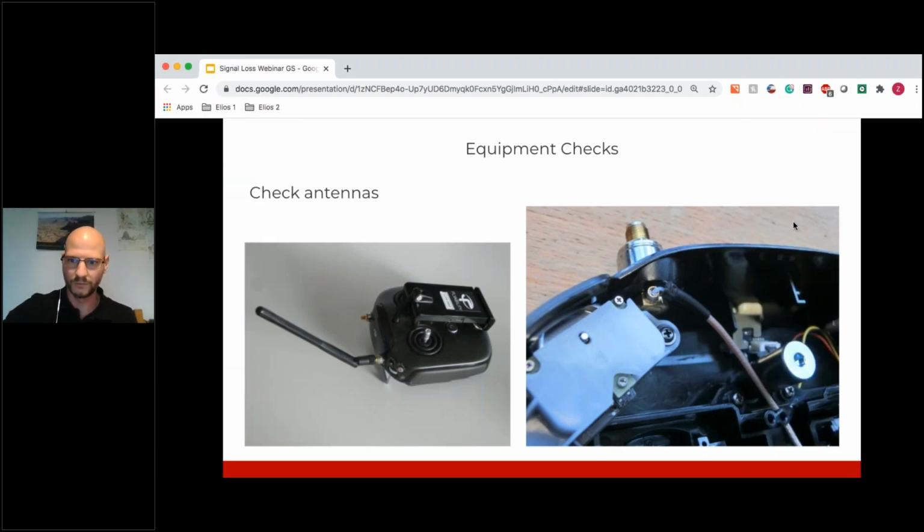If you overdo that, it'll eventually lead to internal hardware failures. So make sure you don't tighten the antennas too much, or cause the entire connector to rotate as you're tightening them.